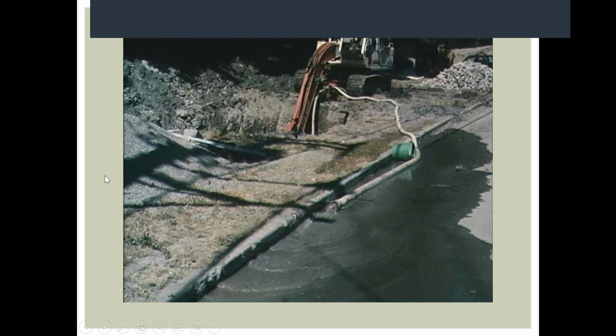This is always a bad thing for an inspector to see when you drive up: okay, what are we pumping out here? This water wasn't real bad, but it did not meet the 25 NTUs for sure. And in this case, we're pumping out tidally influenced water, groundwater. So keep an eye on these sorts of things, and work with the contractor to help them figure out what to do if they need to dewater. What are their options? Is there an area on the site they can pump it to? Is there vegetation? Can they use it for dust control somewhere? Whatever. But pumping it into the street is generally not a good idea.